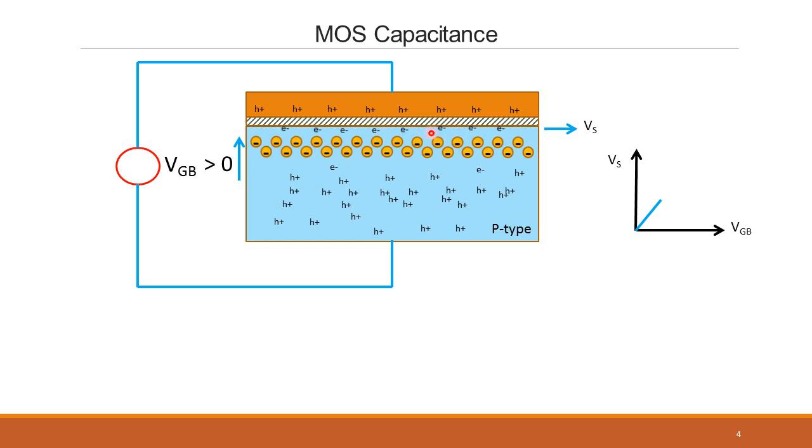a whole lot of electrons will now get accumulated here from the electron-hole pairs that were there. Remember, at room temperature, there's a lot of generation also happening. Right? Generation and recombination both are happening, but generation is happening, and electron-hole pairs are always getting formed. But the field is sufficiently high, so some of these electrons which were generated by the electron-hole generation get attracted to the surface. Right? The depletion region is pushed down a little bit because a thin layer of electrons now gets accumulated on the surface. When this happens, you can call it an inversion region here.